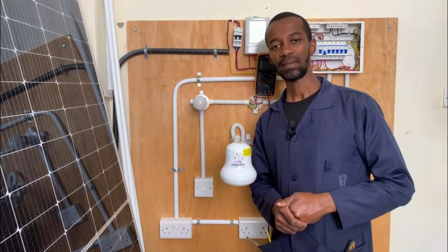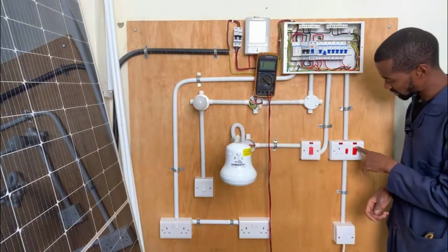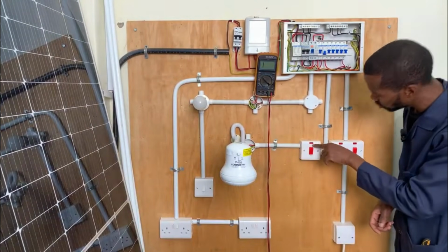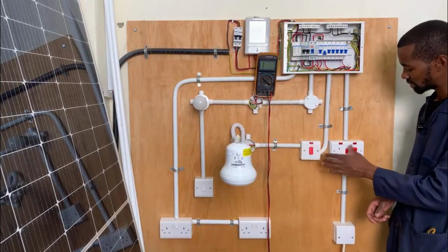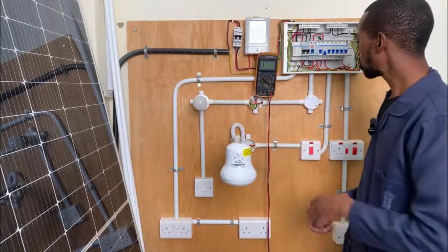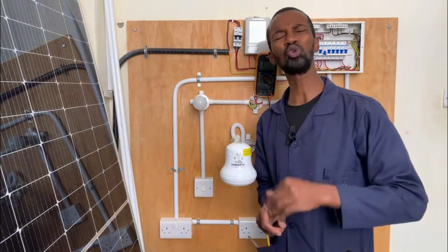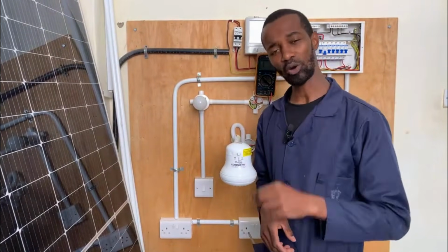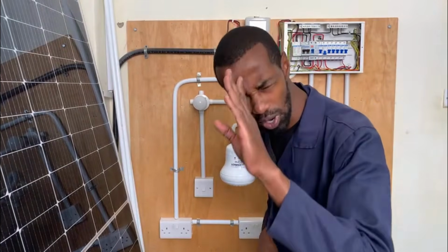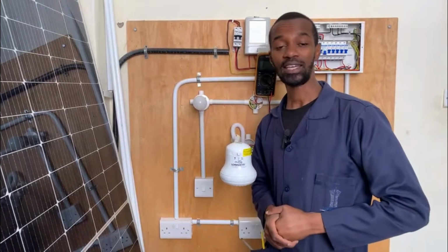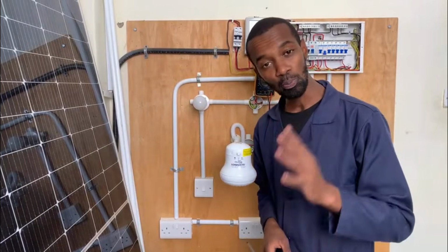But if they say the cooker unit, this one, is not powering on, as you can see, is the shower head powering on? You put on that and it is powering on, then it means that there's a problem with that circuit. You go to the consumer unit as the electrician and you find that there is a breaker that has tripped. You do not lift that breaker or power it on before you find where the fault is. Isolate the cooker. If it is serving a kitchen where you have the microwave, isolate the microwave. Do not rush to power things on.